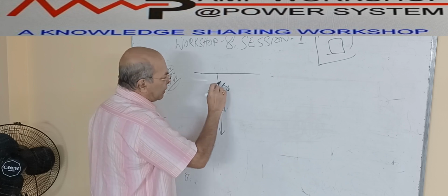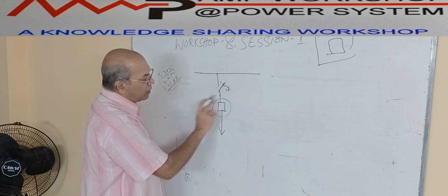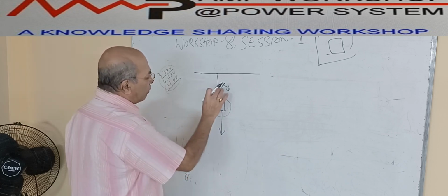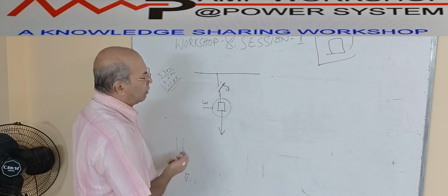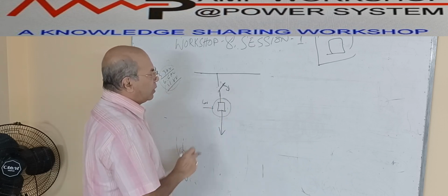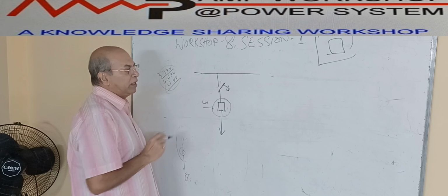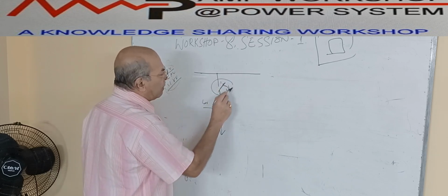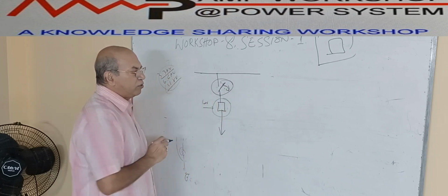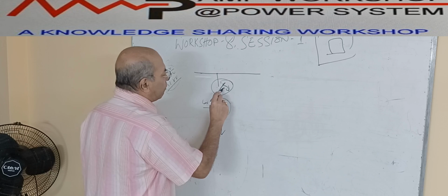So the power supply is disconnected, then the breaker has only control supply, so we can do the testing. In this position we call it the isolated position because it is totally isolated. We can lock in this position. So to incorporate this test and isolated position condition, we have to incorporate another device over here. This device we call an isolator, and with the isolator we put another position.